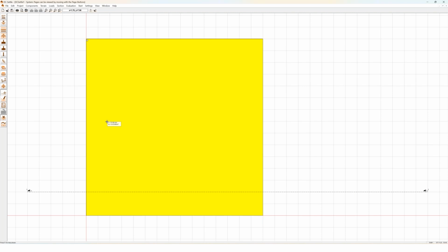We can edit the bottom depths of the soil layers at certain points with this function here with the bore points. We cannot change the order of the layers. We can only change the depth. The order of the layers must be the same in every bore point, but we can have different depths of the bottom of the layers. So we have different layer thicknesses.